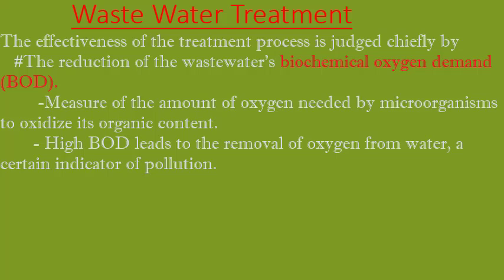So BOD represents the quantity of dissolved oxygen consumed by bacteria and other microorganisms as they decompose organic substances in a water sample over a specified period of time. A high BOD indicates significant organic pollution, often caused by sewage, industrial discharge, or agricultural runoff. A low BOD suggests cleaner water with a low level of organic matter. That means the water in this instance is less polluted.